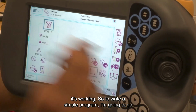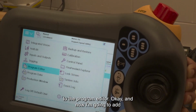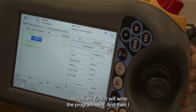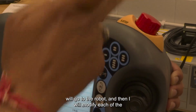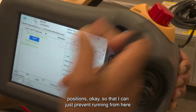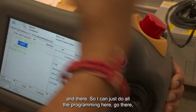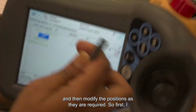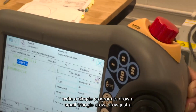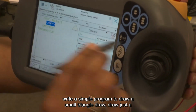So, to write a simple program, I am going to go to the program editor, okay, and now I am going to add instruction. First I will write the program here, and then I will go to the robot, and then I will modify each of the positions, so that I can prevent running from here and there. So, I can do all the programming here, go there and then modify the positions as required. So, first I need to visualize how to write the program. Now, I am going to write a simple program to draw a small triangle.